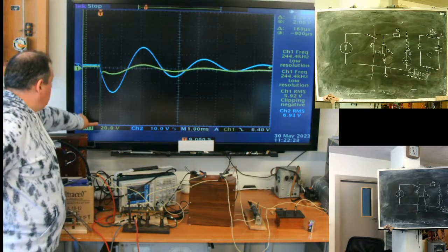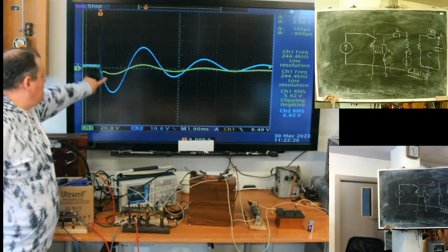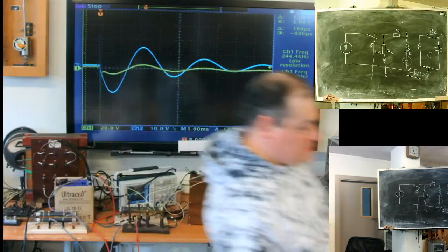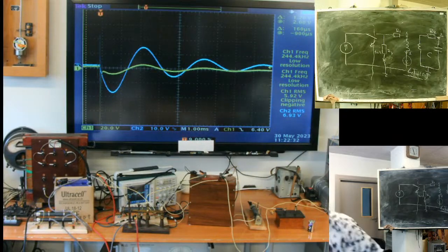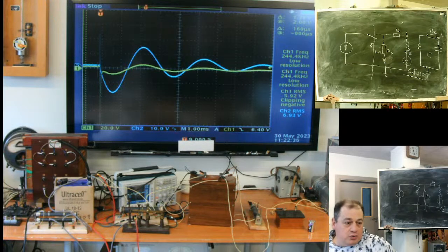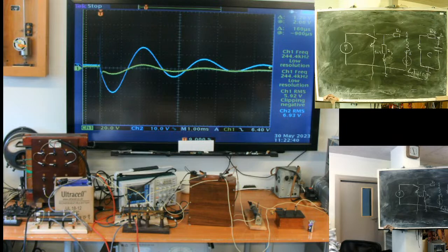But you can see a short spike in lines on the primary side and decaying oscillations on the secondary. Should be up to 300 volts. How deep does the spike go? Looks quite deep.